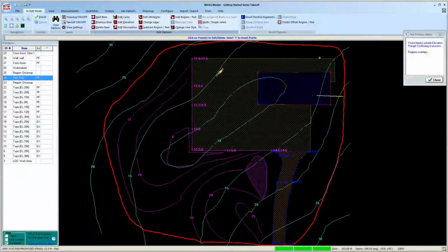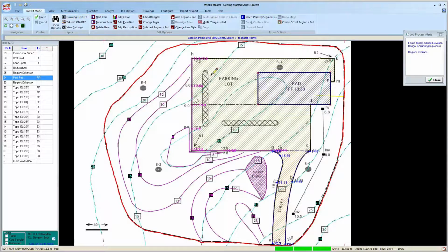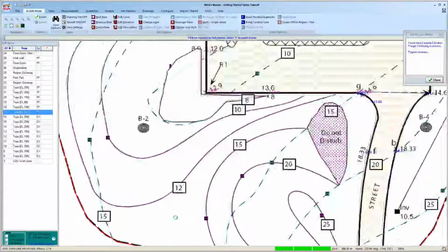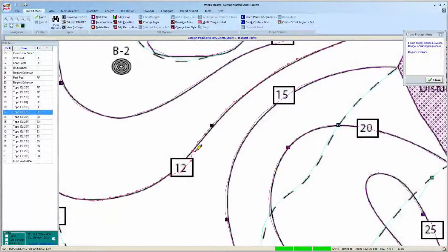Other common uses for the edit mode is to adjust current line work. For instance, if we turn the drawing on, we can see that we've actually followed slightly incorrectly in this topographic line. If we select the line, zoom in, we'll see that this line is made up of lines connected by squares. Select inside the square once to highlight and again to move.